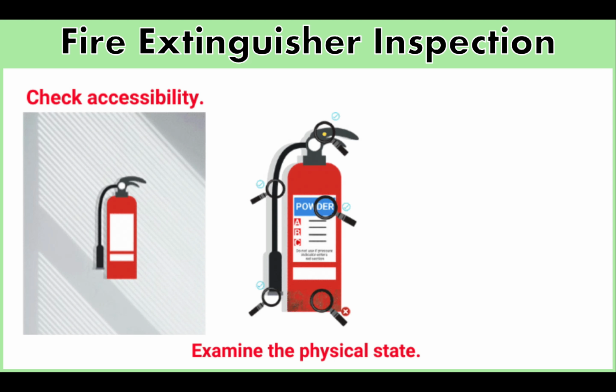Lastly, you have to check if the locking pin goes through the holes of the discharge lever and the handle. Okay, check if the pin is secured well by the seal. The pin locks the discharge lever and prevents accidental discharge.